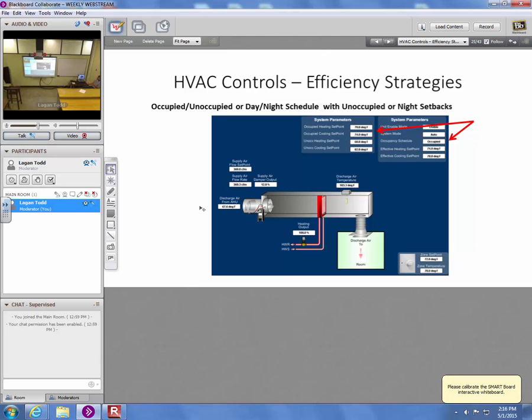It's not really going to heat or cool the space. If you're trying to maintain the space at 70, you can dump 65-degree air into a lot of office spaces, and it won't cool because you have enough internal heat gain that it becomes kind of the neutral point. 65-degree air coming in will hold the space at about 70, which is good. Actually, I should have said that a little differently. A certain minimum amount of 65-degree air won't cool the space. So this sends just enough 65-degree air in at all times for ventilation.